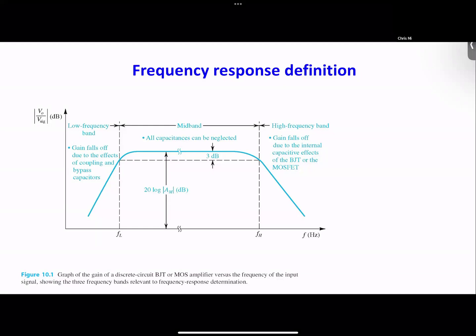The one you buy might work for 100 kilohertz. But if we wanted to design, say, some Wi-Fi stuff that works at gigahertz, 2.4 gigahertz, your device will never work because it only works here, but your frequency is way over here. So you need to select a different device that works over here, okay? So we want to find out how our device responds to different frequencies.